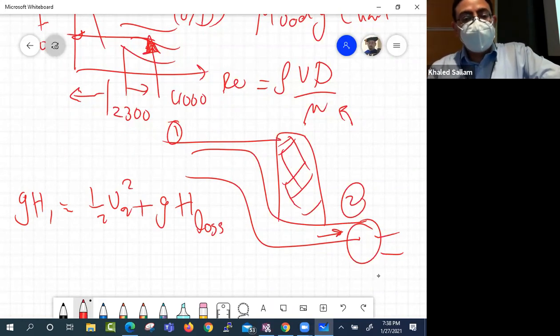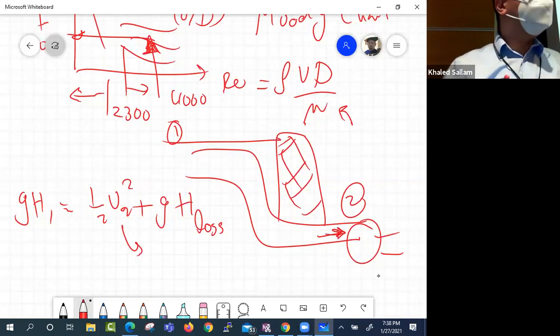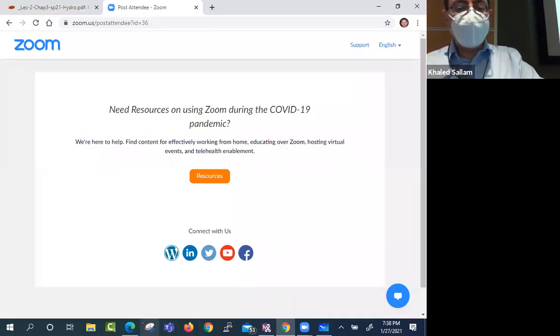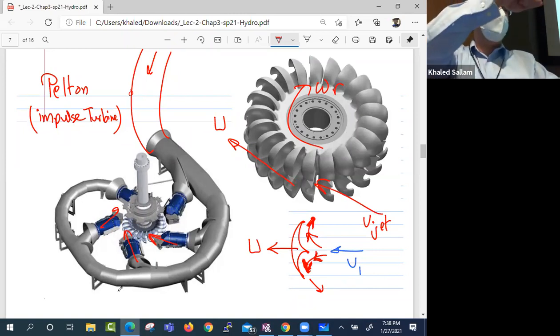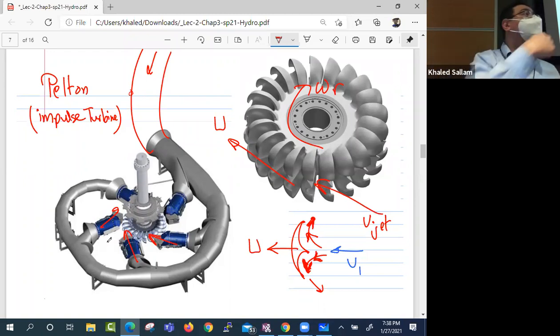All right. So then that V2 is the kinetic energy that will have to be, I mean, it's nice that it's moving fast, but if we shoot it fast into the turbine, it will break the turbine and we are not going to get any spinning. So now we need to shoot it with, this is called a Pelton wheel. And it's just a bunch of pockets. And it's shooting the jet not in the pipe, or sorry, on the turbine, but tangentially to the turbine. Why? Again, it wants to generate this kind of angular momentum, right?